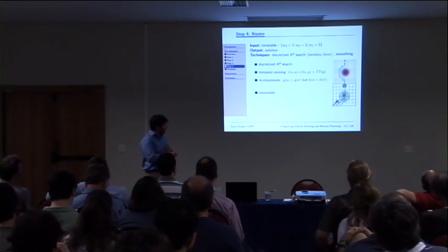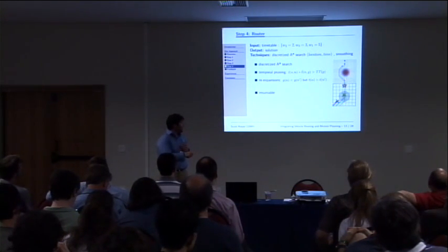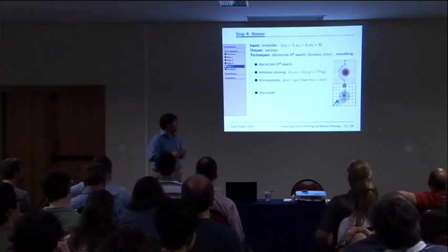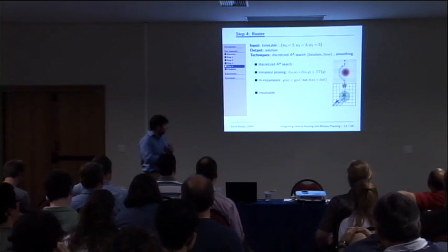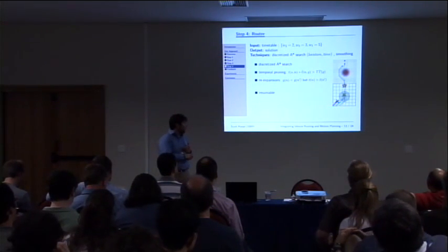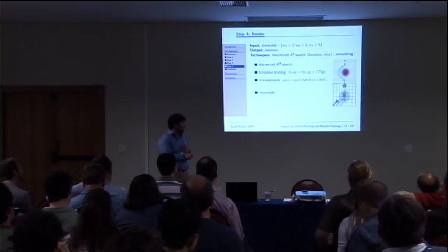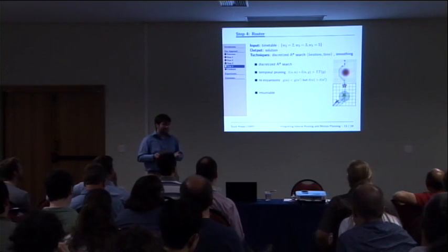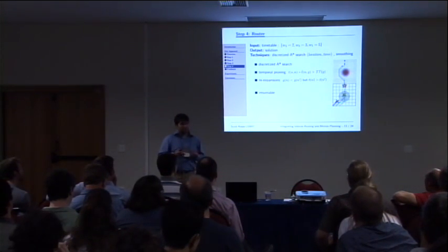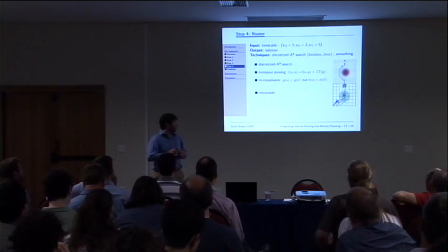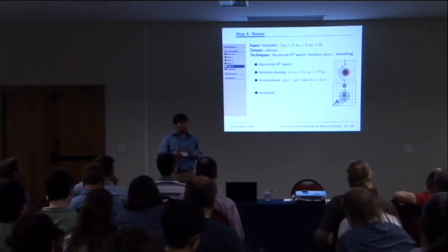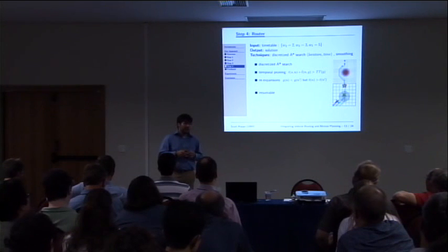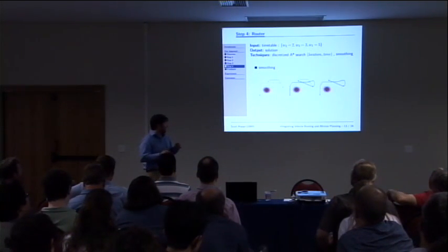So we have to explore more of this path at a more costly route until we can finally find a path from the start to the waypoint, respecting the upper bound on the time. Here we can see that we'll have to re-expand this node at a higher cost, but an earlier time. Also, because of the smoothing step that I'll talk about in just a minute, we keep this A-star search resumable. That just means we keep the open list and the closed list around, so we can continue the search if we need to. And this is exactly why.